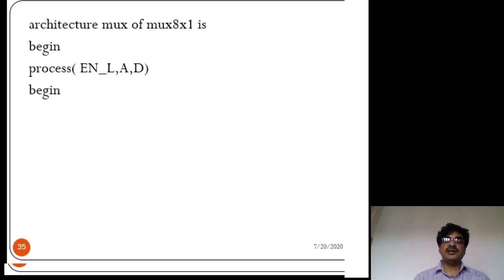Okay, here I am going to check first of all the enable input. If the enable input is 1, the IC is inactive. Okay, so the corresponding outputs are Y is 0, Y bar is 1. Okay, suppose if the enable input is 0, that is the IC is in enable mode, so that it shows the multiplexer action.